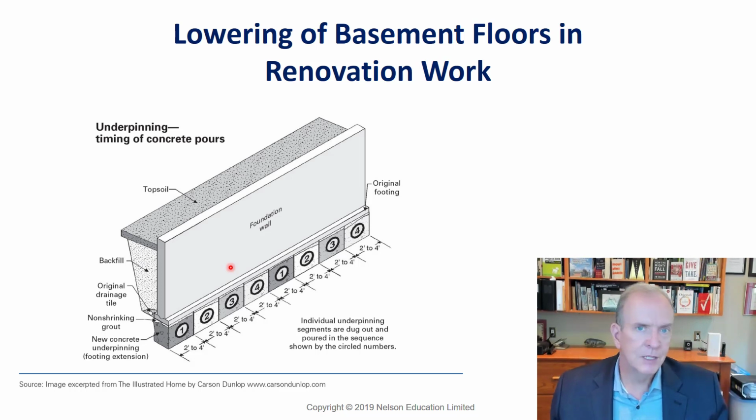There's no point in finishing the basement if everybody's got to be crawling around trying to duck around the ductwork and piping. So you can't excavate underneath an existing foundation completely because it would just collapse. So what we do is we actually measure around the foundation, and we do markings. So we'll do 1, 2, 3, 4, usually at spacing of around 2.5 feet to 3 feet. So the spacing's usually around that wide, and you excavate out underneath the foundation.